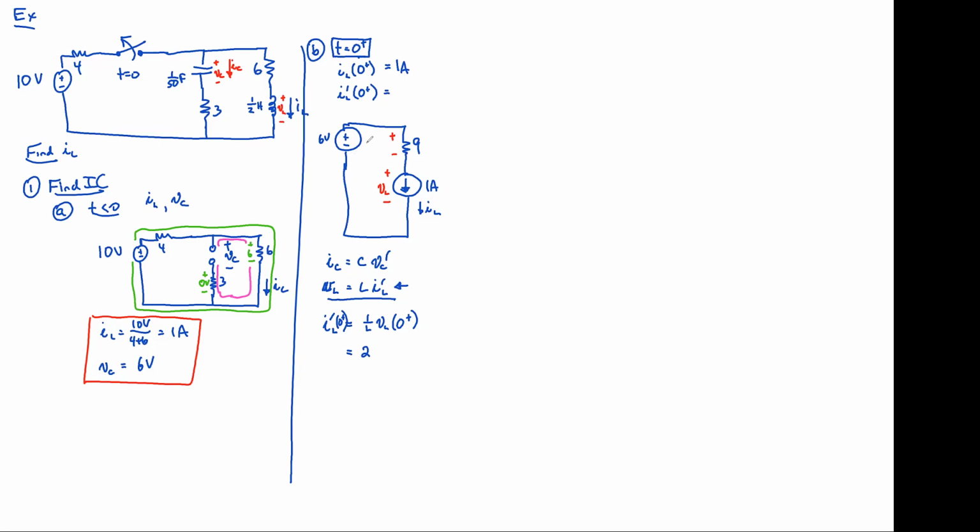We know all the voltages here, here. We just don't know the voltage here, and we could solve it. But what's the voltage across the 9 ohm? Since there's 1 amp flowing there, wouldn't it be 9 volts? So by Ohm's law, it has to be 9 volts. Now we can write, if you're good, you can just see it, but it's easy to get signs wrong, so let's write it up. Starting at the negative side of our 6 volts, we get -6 plus 9 plus V sub L equals 0. Therefore V sub L has got to be equal to -3 volts.